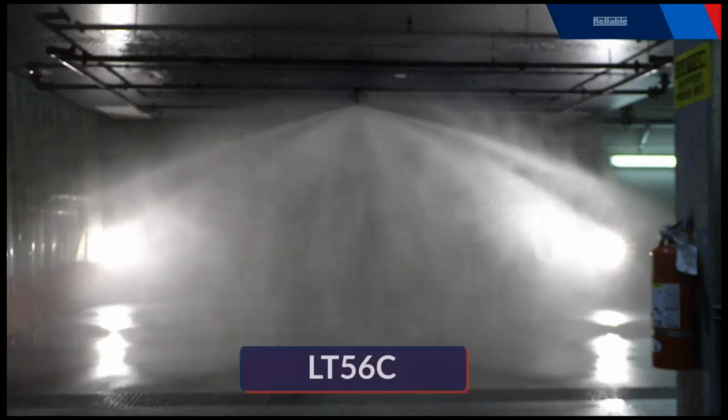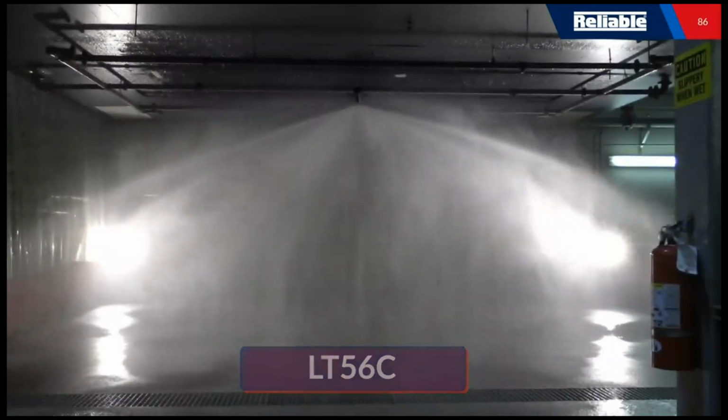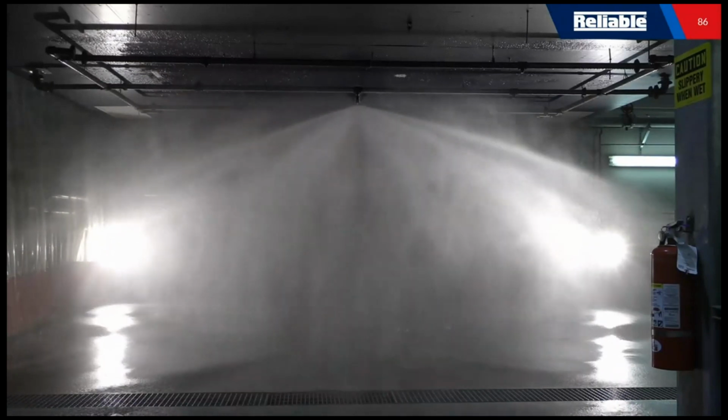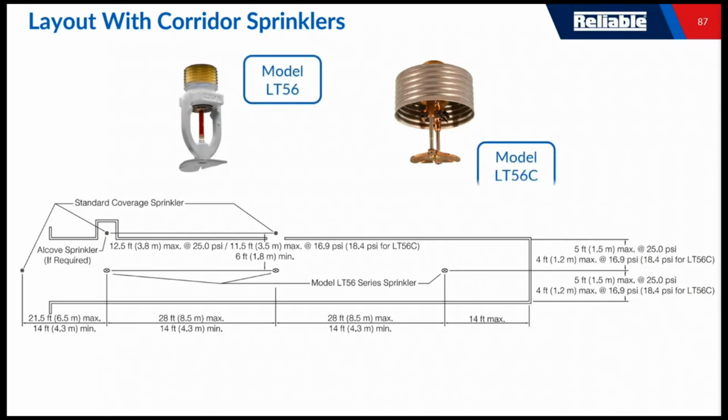And if you take a look at the spray pattern there, it's very narrow and it's very wide. So that gives you the ability to place this in a corridor. And the ability to space them 28 feet apart just allows you to skip a lot of sprinklers in a long run down a corridor. That's really the only acceptable way to install these products as well. It's just a long throw product that's meant to space 28 feet in between them at a maximum. So there's no rotating these 90 degrees and stacking them in a room, similar to the attic sprinkler concept. It's just this one way right down a hall.